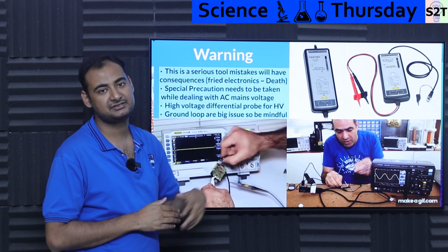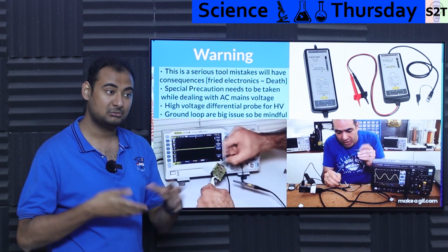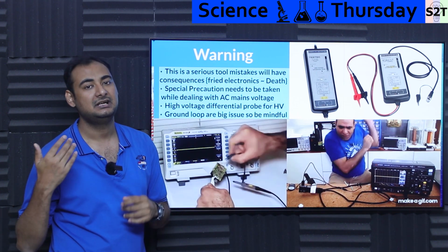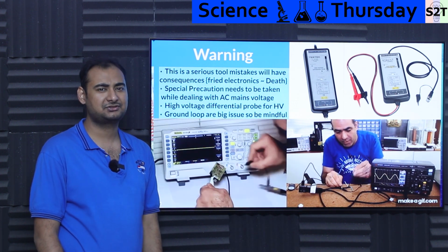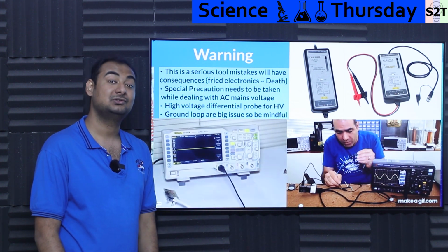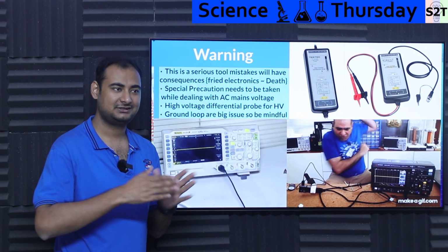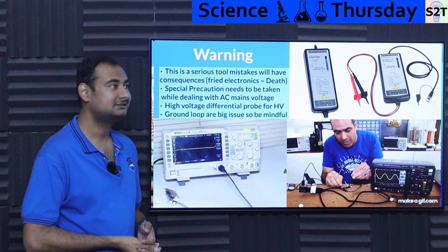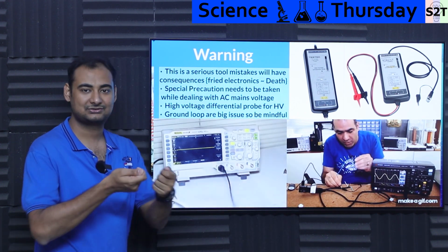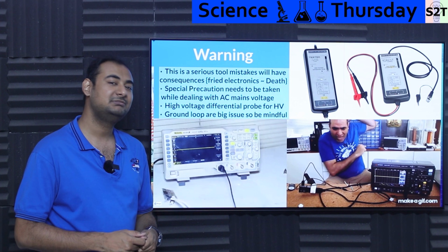And these are the cheap variants. There are some expensive ones which are designed with much higher grade insulation so it can handle high DC offset voltage like 1500 volt DC. Like who the heck works with 1500 volt DC? Come to solar panels. Solar panels nowadays, a string voltage can easily reach that point. So if you need to see something like that, yeah, do not just use your oscilloscope and go like this. Yeah, that may be the last thing you do.